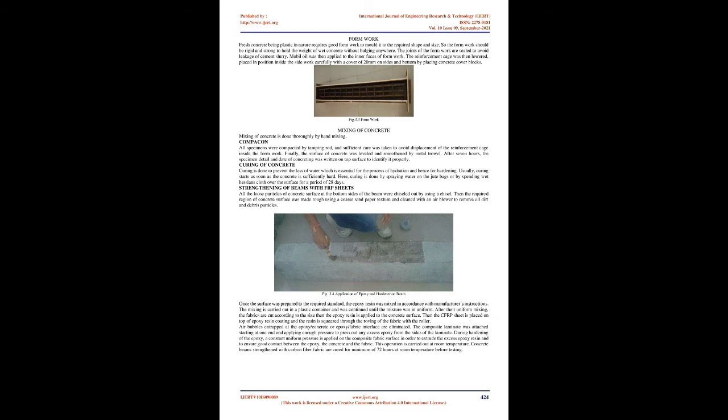CFRP is widely used to strengthen concrete structures that have lost reinforcing steel mass due to corrosion and concrete deterioration because CFRP possess good rigidity, high strength, low density, corrosion resistance, vibration resistance, high ultimate strain, high fatigue resistance, and low thermal conductivity. They are bad conductors of electricity and are non-magnetic.